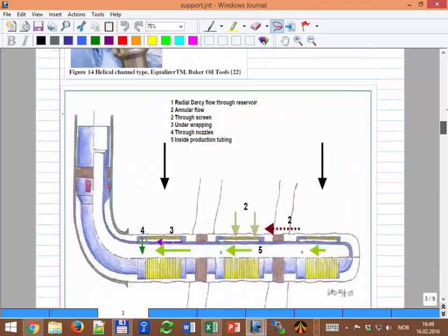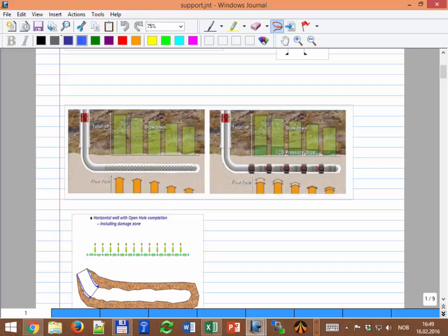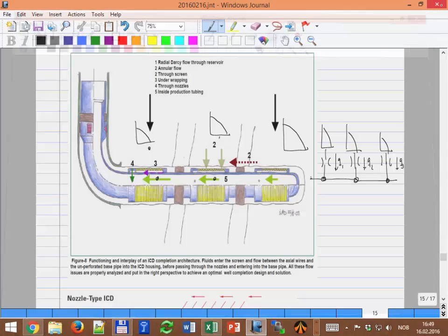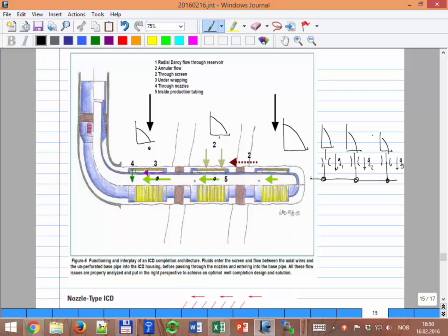I think allocation you leave for next week. So maybe to summarize, we saw today one example with networks. We saw three cases. We saw natural flow, where there is a unique solution, and I showed you how to calculate it. Then we said fixed rate, and then we have to calculate choke opening. And then we saw one case with boosting that was kind of half and half. One part was natural flow, and the other part was fixed rate.